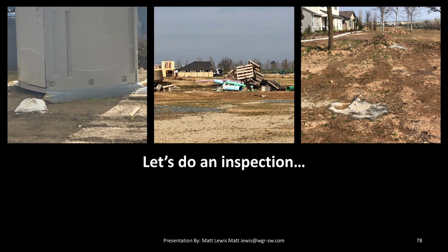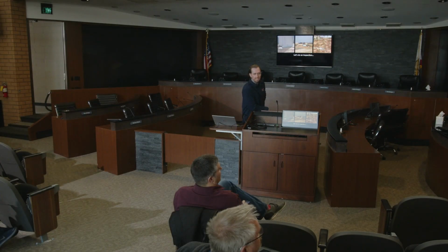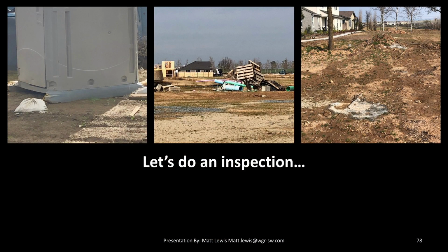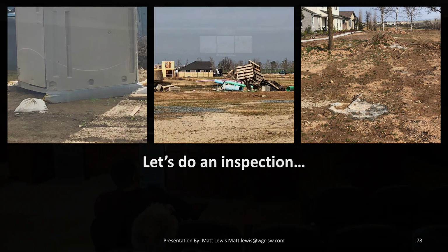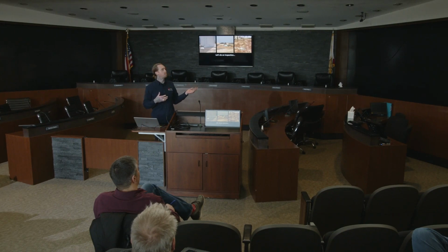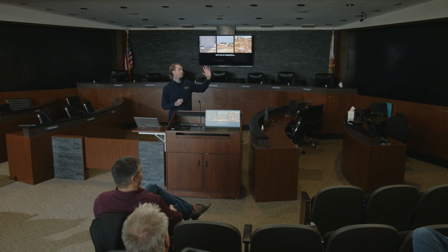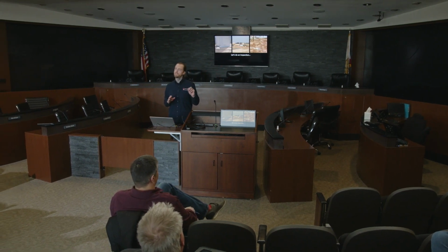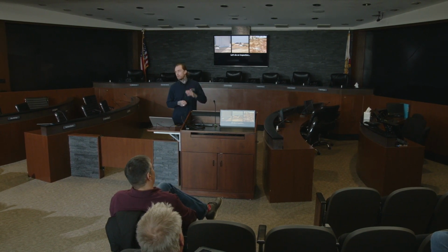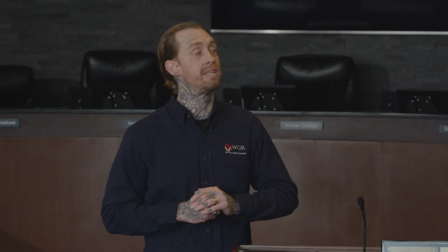So what do you see on that porta potty? There's one thing missing. No secondary container, that's it. And as I had mentioned with Brandon earlier, technically porta potties need to be fastened down. They should be roped with sandbags or staked into the ground, because a dumped over porta potty is something that no one ever wants to deal with. And that's actually a non-visible pollutant sample, which is a sample that has to go to the lab, and it's quite expensive. So porta potties should always be fastened down if you can help it.